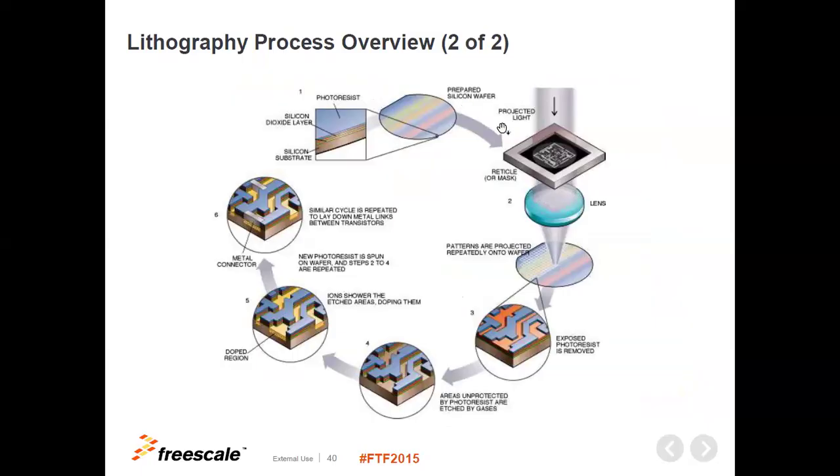In a nutshell, on what I was telling you: we have the buffer that we can put a photoresist on top of. The photoresist is going to create the base for creating the tracks. Then with the laser and lens, I can selectively remove the photoresist, okay? The photoresist is basically going to isolate the upper part of the buffer, okay?